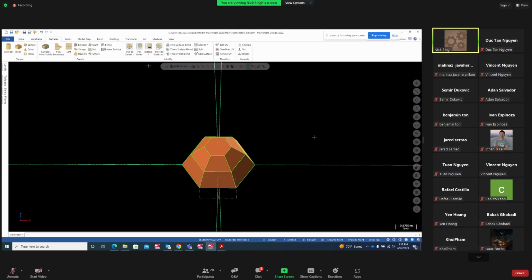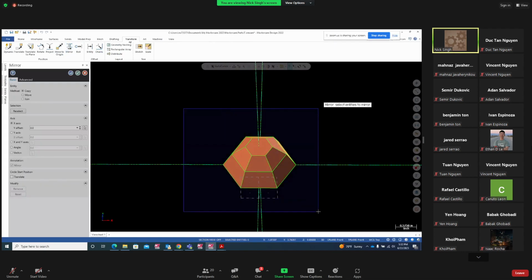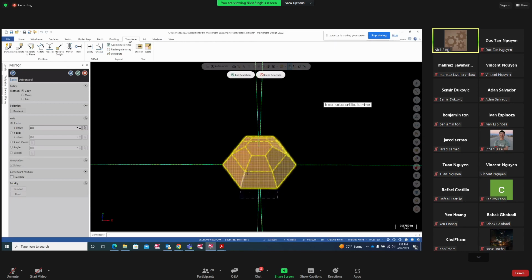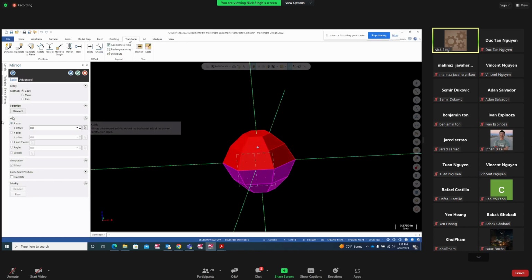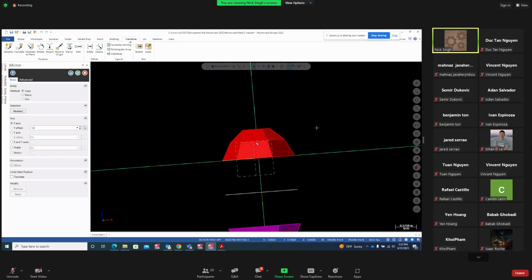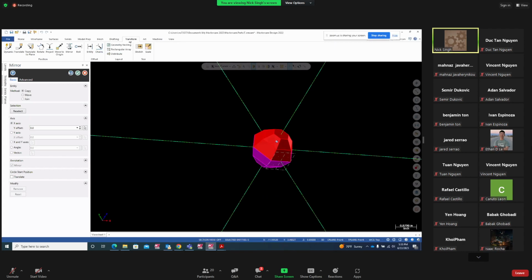Okay, hit your escape key and let's go back to transform. We're going to go to mirror and I'm going to select this entire entity with the window in. It will select your surfaces and all the geometry. Hit end selection and there's your option. You already select that mirror to x-axis. Here your y offset, if you say -1 inch y, it will mirror that, but split those 1 inch and 1 inch apart. That's what that means. But we're not going to do that. We're going to say distance 0 because we're going to keep them joined. And hit OK.